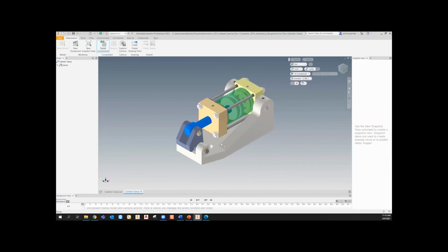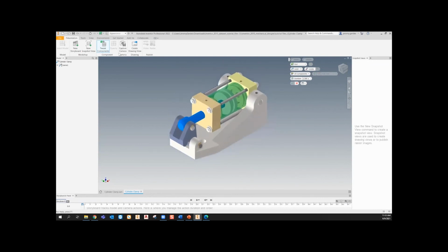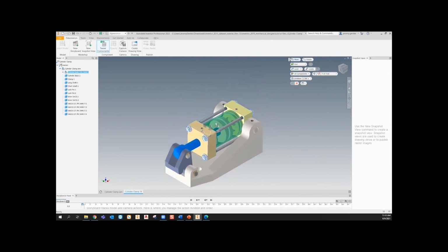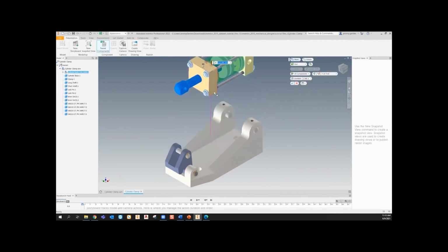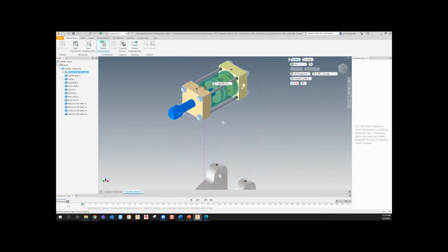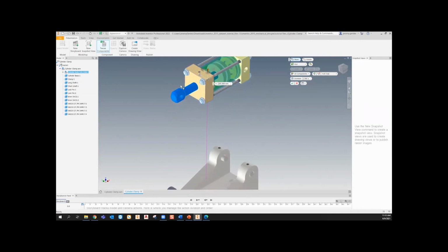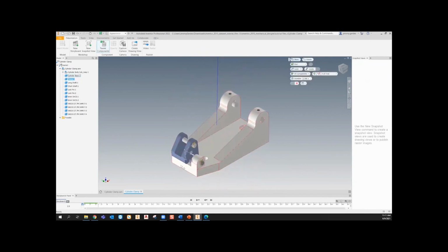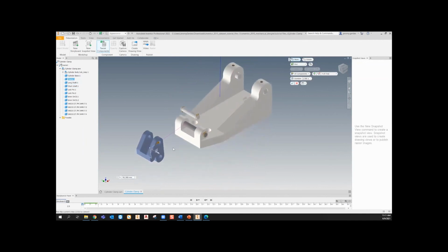So tweak components is what you would use if you're creating an exploded view. So you select the component and we're going to say it'll be this subassembly, and I'm going to bring it up here. I can show the trails or not. It's up to you and the company. And hit OK. I can tweak this component. And say it comes out here. Hit OK.